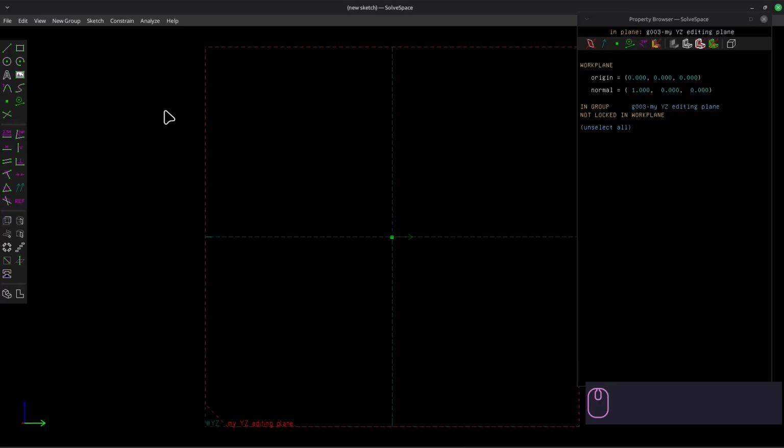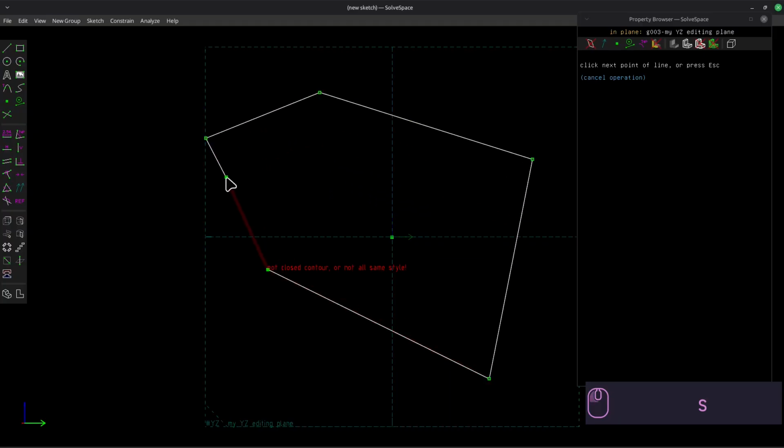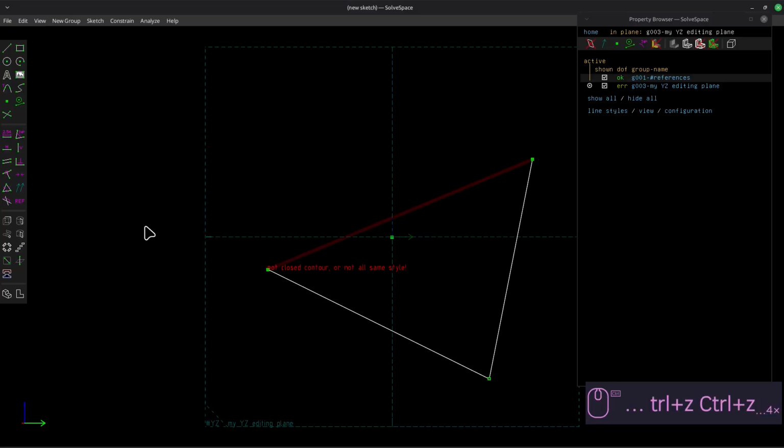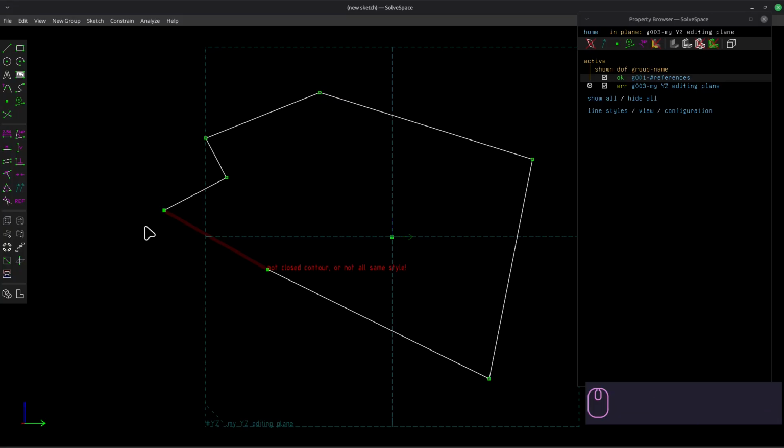One more key idea. Well, let me draw some lines. To undo an action that you've taken, press Ctrl-Z. And to redo an action that's been taken that you've deleted, press Ctrl-Y. So Ctrl-Z deletes the actions that were taken, and Ctrl-Y recovers actions that you might have deleted in excess. See how all the lines are located on a plane?